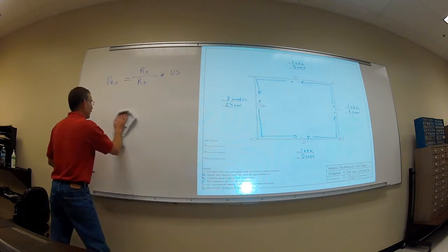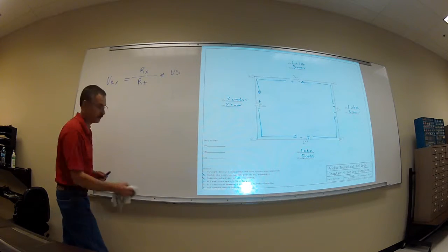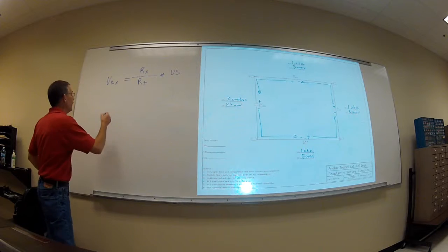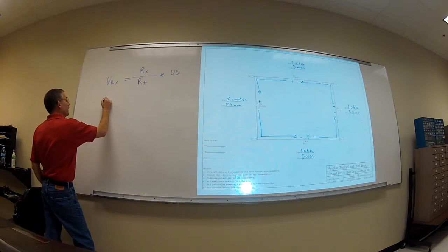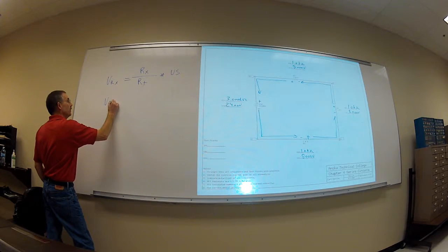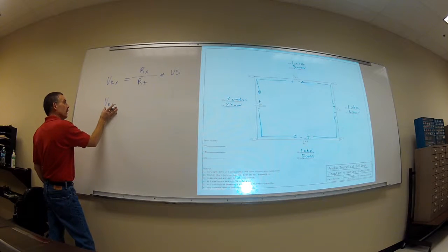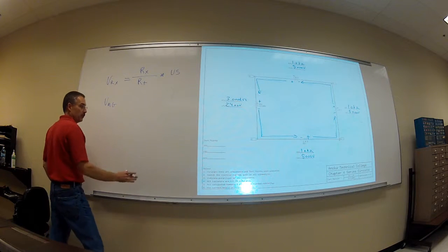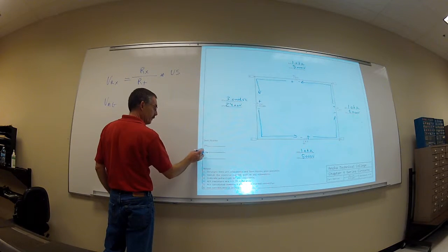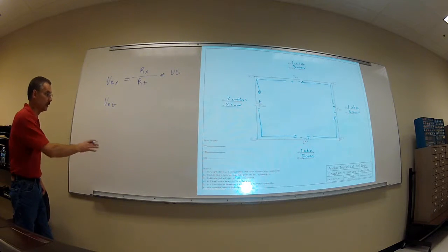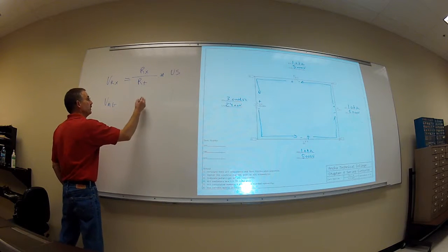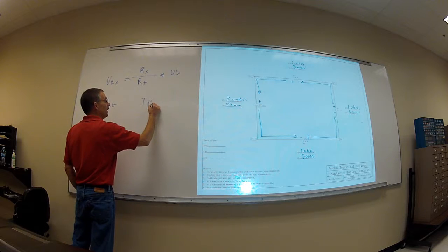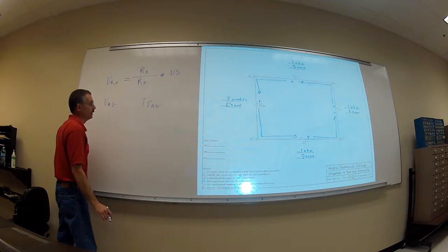Now we're going to find out what our test point voltages would be. Find out what your test point voltages are. We'll use VAG here. Typically there are subscripts there whenever it's possible. I can't do subscripts in this program here. So you just have to make the assumption that it's measuring my voltage at test points A and G. I can also have it as, you might see it as TP AG. Okay?